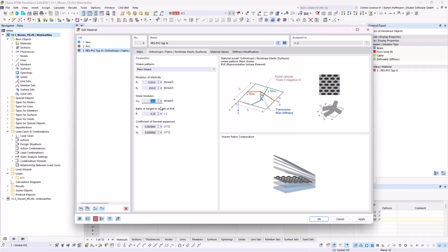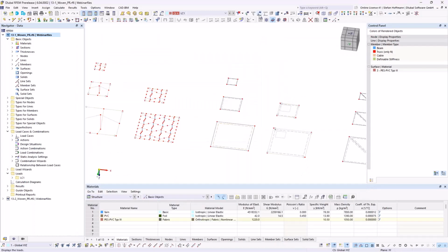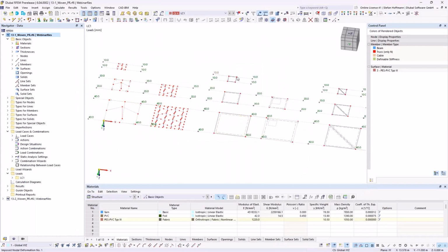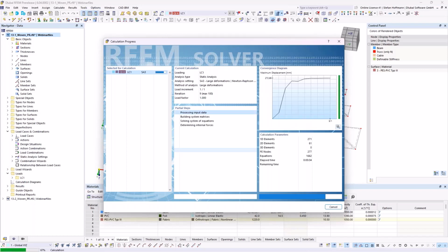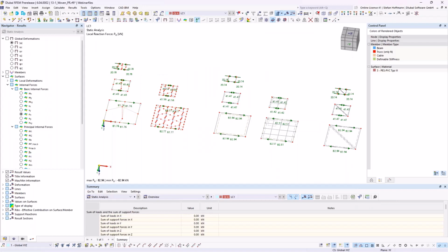You can define a coating if you want to, and you can define a ratio of this. So this one is an example to test, if we have now support movement, what results can be achieved with the nonlinear material model compared to the element which is in the background. It will not fully match, depending, of course, on the type of convergence where you then will set your equilibrium. But you can maybe see in the support forces we are close to reasonable results.